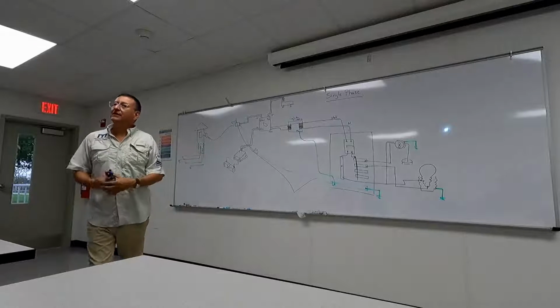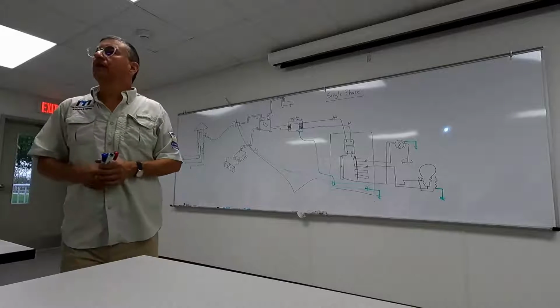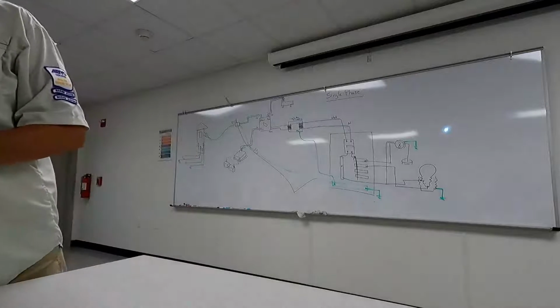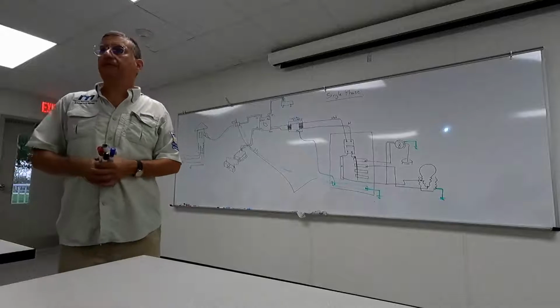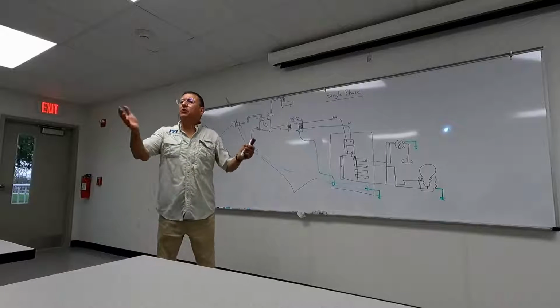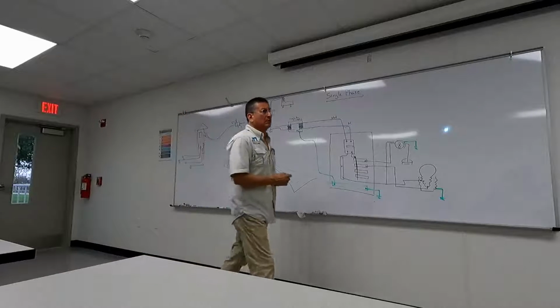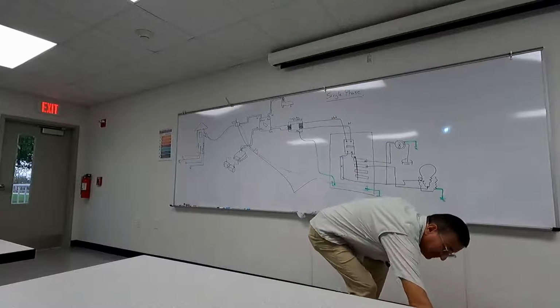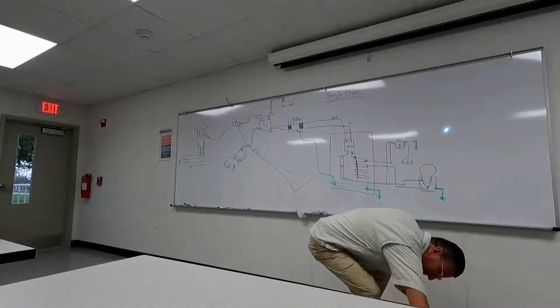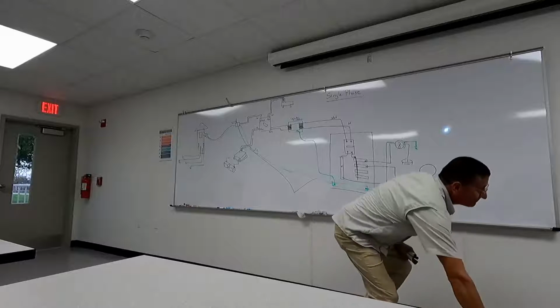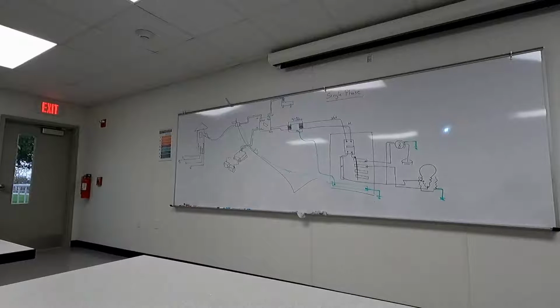Do you need a galvanic isolator if you only have DC in your boat? If you have AC. No. Only AC. I have a small boat. Yeah, the only time you see galvanic isolators is probably on boats 50 feet and up. On my end of the industry, I don't see the isolation transformer.